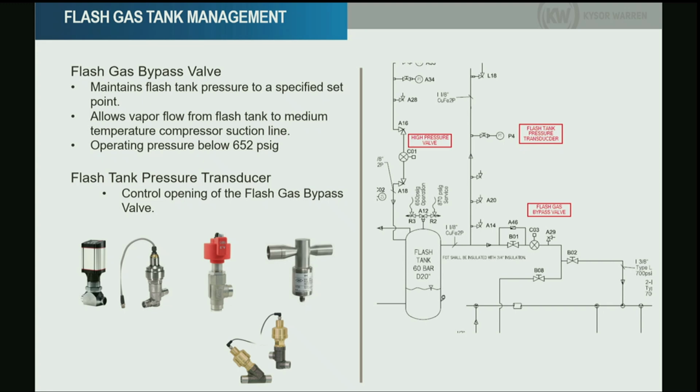In some cases, the difference is just the pressure rating they are applied for. Like these Danfoss valves, some are called CCMT, with a T at the end. For the flash gas bypass, they are only CCM. The T means transcritical, which goes on the high side. The non-T means subcritical, which is lower pressure rating only.